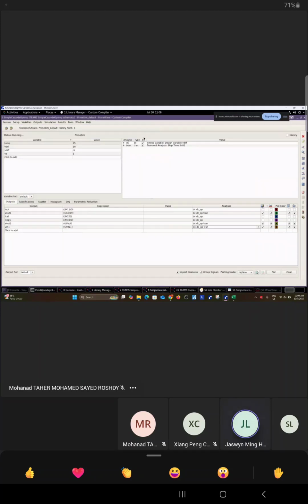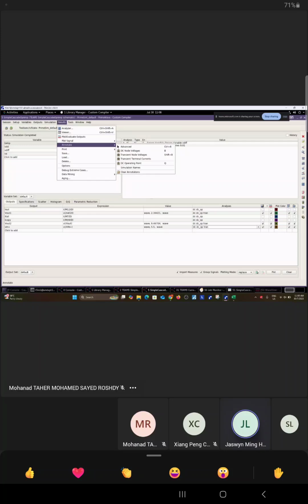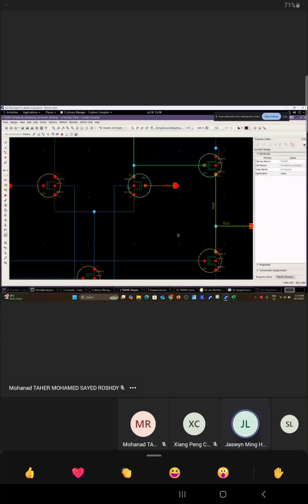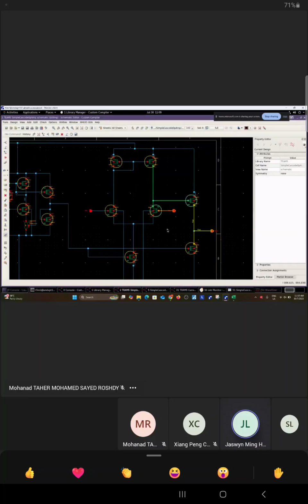Previously, when you showed me that V in plus and V in minus are all at common mode, from what I noticed, now I realize it. At common mode voltage for both sides, you just need to ensure your tail current MOSFET is in saturation. That's it. For this part, I won't be worried about it. Most likely you are hitting the cap, hitting the max or min.